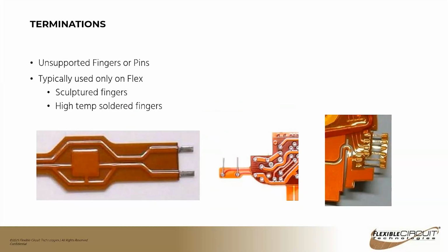And then unsupported fingers or pins. Typically, this is only in flex. It wouldn't be in rigid applications or rigid flex applications. It could be either sculpted fingers, so the actual conductor material itself extends beyond the edge of the part, or it could be a secondary finger or pin that gets soldered on afterwards.